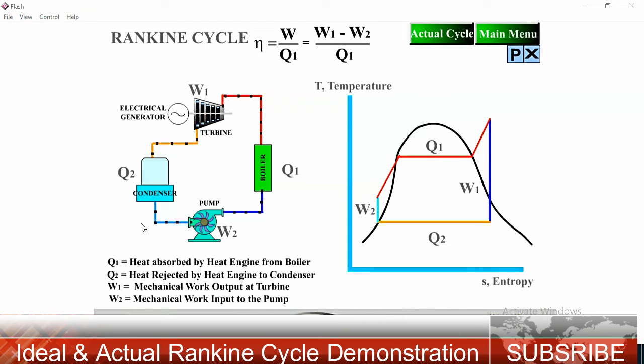Because of condensation, the condenser pressure is easily maintained at about 1/10 of atmospheric pressure. Water leaves the condenser in the saturated liquid state. So for state 3 to 4, the saturated liquid from the condenser is pressurized in the pump to the pressure at which the heat addition process will take place. Ideally, this process is isentropic.